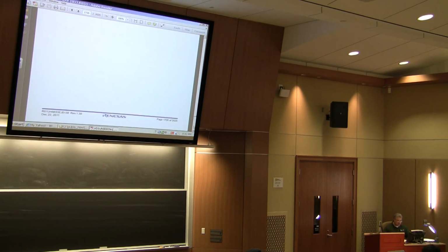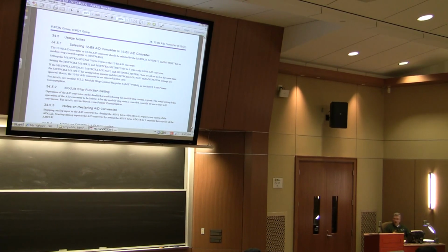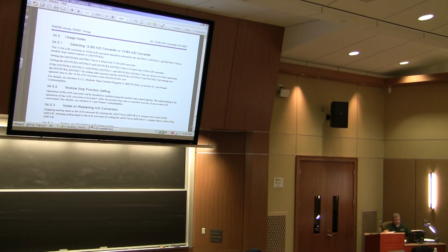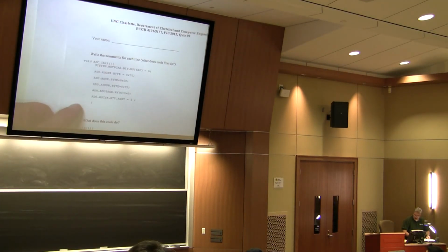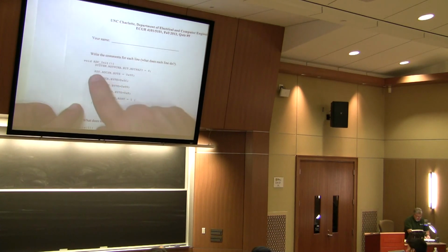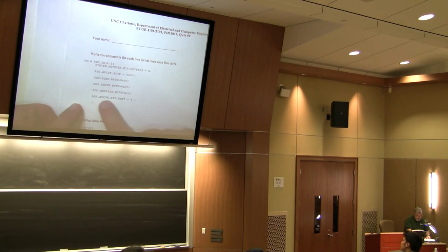The other thing is when you're starting to look at hardware, it gets a little bit more complex. So what I will do is I will give you the following information to ponder for the upcoming exam. And that is, if you have the following setups of code, what do you think this does? Well, we already talked about this line right here. That's how you set up the register. Oh, look at this. That's the same register, but we're looking at a single bit, and the ADST said what? Start a conversion, right? And we set it to 1.